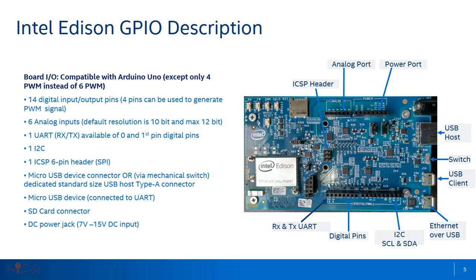If we keep this mechanical switch towards the USB client port, the board will act as a device, while if we keep this switch towards the host port, the board will act in host mode. The next micro USB port is for serial communication and also Ethernet over USB.